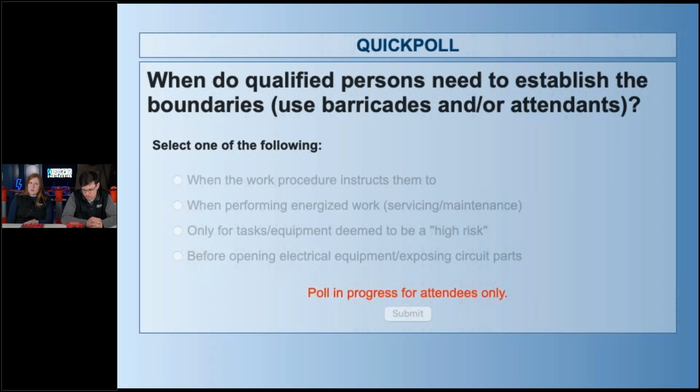I see a lot of people misuse the tables method. And honestly, if you have all that information, just plug it into the program and hit calculate and you get your incident energy. The more complete study, more complete analysis. And I think the question is what code sets the boundaries, possibly. So obviously the arc flash study is going to give you the results through the IEEE 1584, and the 70E has determined where that cutoff is. And then OSHA and 70E for the shock boundaries are consistent as far as how far out those hazards are considered present.